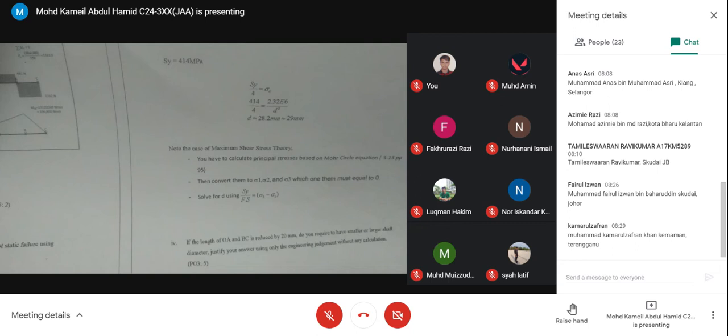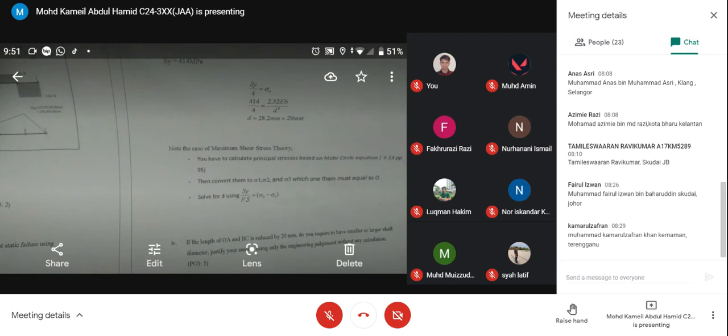Do you understand? Because in all this analysis we look at the maximum loading. If the load is bigger, the shaft must be bigger. But if the loading gets smaller, and moment depends on the distance, force times the distance, once you reduce the length, your structure or component will have less load. The moment is less, so you can use a smaller shaft.